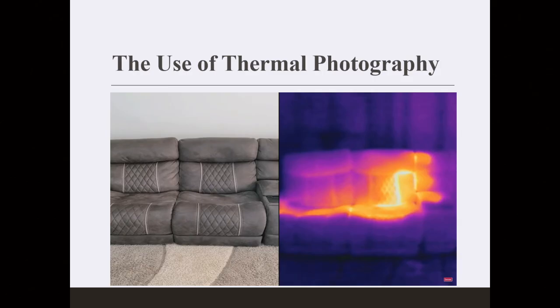The way manufacturers advertise it, they go to a wall like this, take a picture, and it will show, let's say, a blue layer, because the temperature is presumably uniform for this board. Then the person who's selling the machine puts his hand on the wall for a few seconds. Then guess what's going to happen? His body temperature is going to be reflected on the wall. If you take a picture, it will show his hand as a change in temperature, and it tells you roughly what temperature is being spotted.